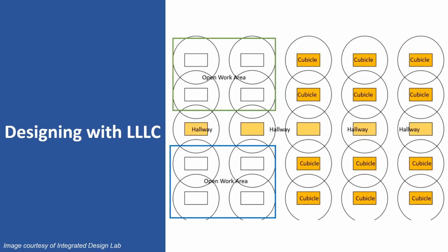As a lighting solution of luminaires, a luminaire-level lighting control system is designed similarly to a standard system. Overall, the lighting must satisfy the owner requirements and basis of design. Attention to detail, however, must be given to aligning task areas and dedicated luminaires. In an open office, for example, a typical luminaire serves 80 to 120 square feet, while the control zone for an onboard occupancy sensor can be limited to a roughly 8 by 8 area, suitable for 10 by 10 workstations.